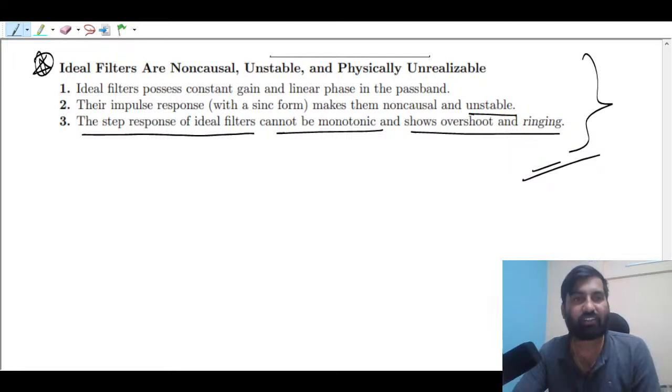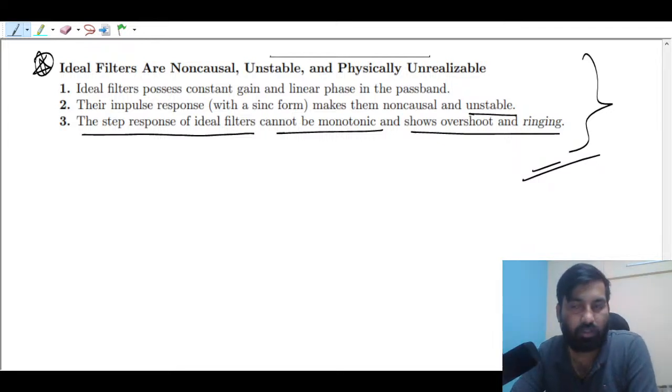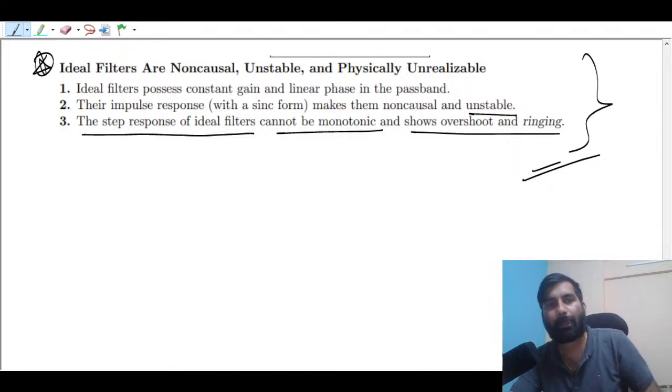So you can also get RC low pass filter, that is single time constant filter, right? You can find out its transfer function also, right? That is very simple. I think it is very simple to find out, right? 1 by 1 plus j omega RC, okay? And then magnitude you can find out, and phase you can find out, right? Simple, okay? So from today remember, what will you remember? Very important to keep in mind, right? Okay,